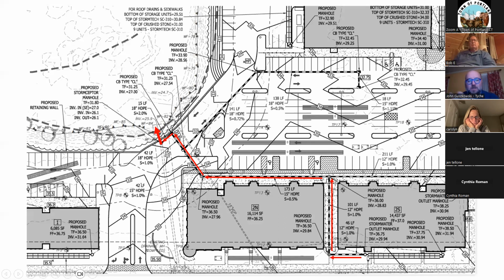And so we basically go, again, water runs downhill. So we pick up water at higher points and pipe it, pitching the drainage so that it slopes downward towards the low point. And again, the catch basin down here is at 31. The catch basins up here are at about 35. So we're running this downhill, down slope, and it will drain out into the wetland area. So anytime you see the drainage, take a look at their various elevations, and you can catch the direction of the proposed drainage based on keep going down slope, keep going down slope.